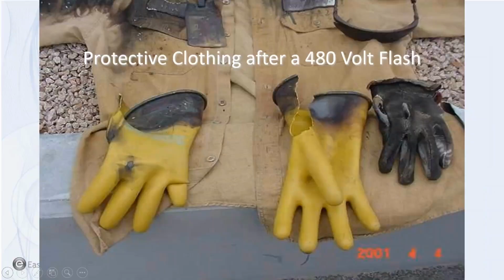This is after a 480 volt arc flash. It was estimated to be over 10 calories. And you can notice that the rubber gloves actually held up pretty good where the leather protector was. You can see the leather protector was damaged pretty badly. But notice this, this is an interesting thing right here. OSHA actually says that you can wear your jewelry, your rings, your watches, and all that as long as you make them non-conductive. So that's an exception to taking them off.